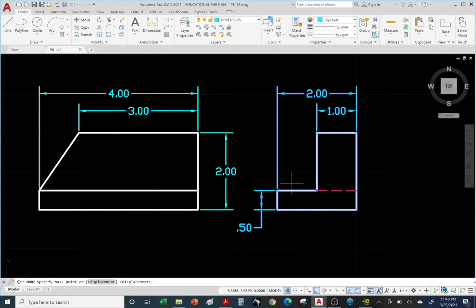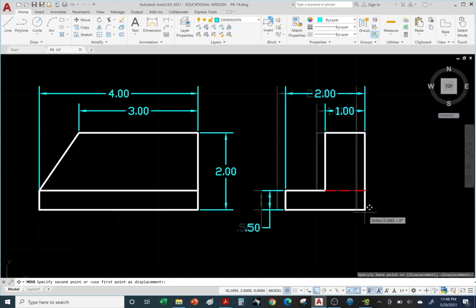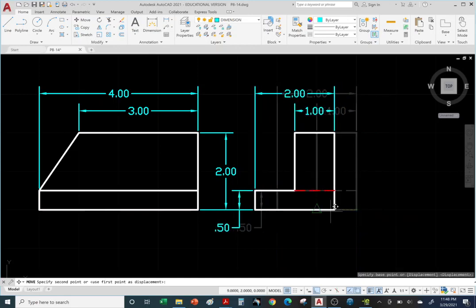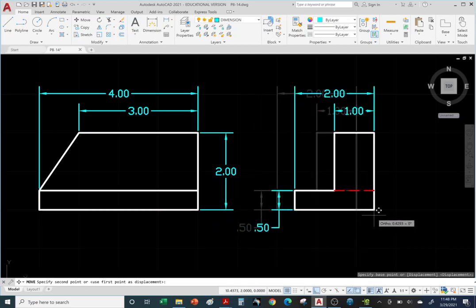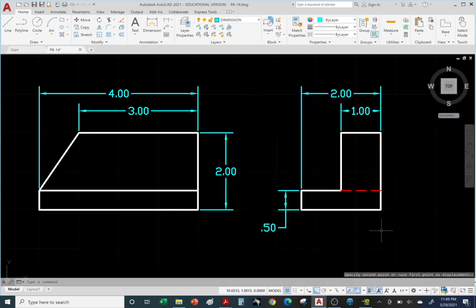And we can just move it towards the right. I'm going to use the move command just to space it out. This is optional. You don't have to do this part. And again, you want to have ortho on, so it allows you to only move vertical or horizontal. Okay, so you have that option to move it over. It looks a lot cleaner. You don't want two couches or a couch and a table too close together. You want to leave some room for walking by. Okay, and hit escape to exit.